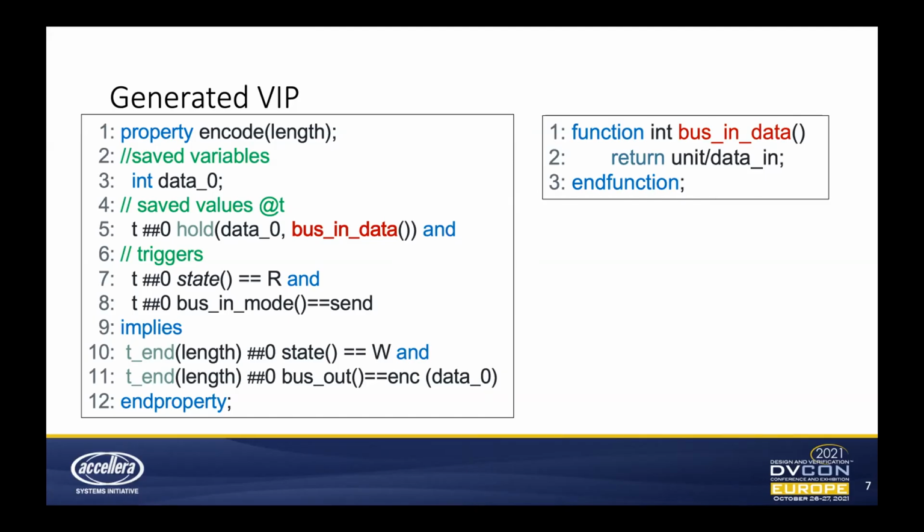But what I would actually like to get to are some concerns many people have when it comes to that idea that, yeah, we're missing many details when we have an abstract asynchronous transaction level model in the beginning. We're missing details that are only visible if you're at the RTL. And how do we cope with that? Well, all the objects that result from the abstract model are represented by functions. And the main task, or the only remaining manual task that you have to do, is to refine and fill out this function and say, okay, how are things actually implemented in the RTL?